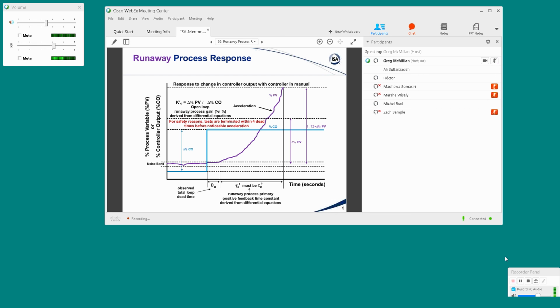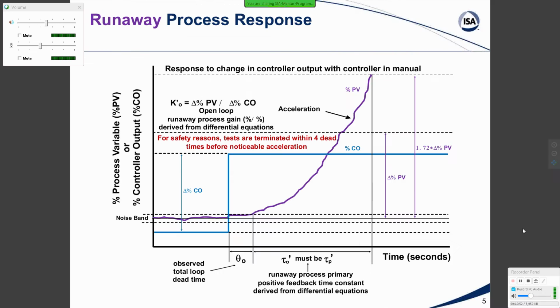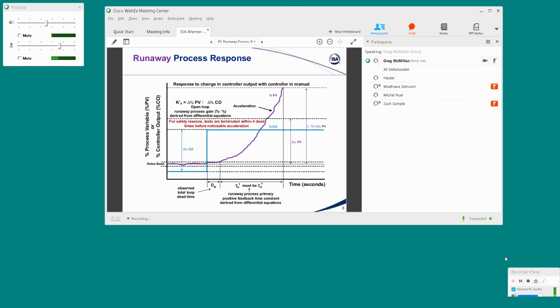That's right, and that was one of the benefits I saw switching to near integrating rules. I was concerned about load disturbance rejection in my processes and the tuning to take advantage of that. And really that's what lambda becomes, an arrest time. Exactly. And so it's saying, how long does it take for you to turn around that response, to stop deviating and to start to return to set point? Yeah, that's a critical thing, and so that was the other aspect of it.